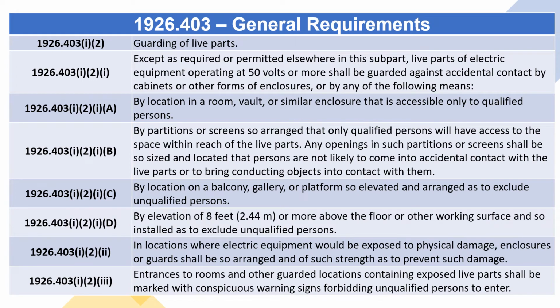(C) By location on a balcony, gallery, or platform so elevated and arranged as to exclude unqualified persons. (D) By elevation of 8 feet (2.44 meters) or more above the floor or other working surface and so installed as to exclude unqualified persons.